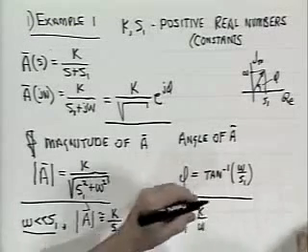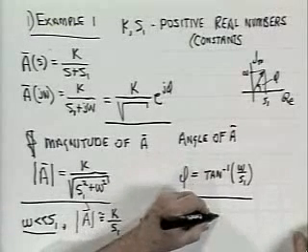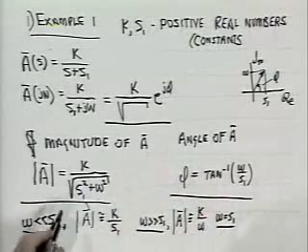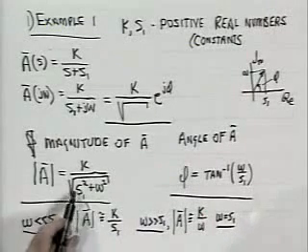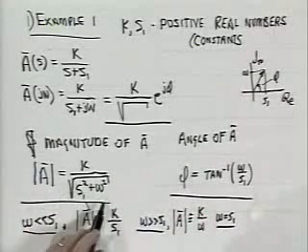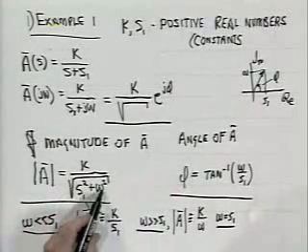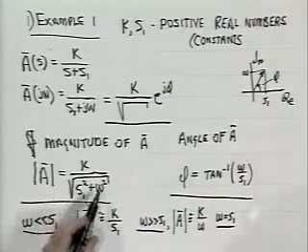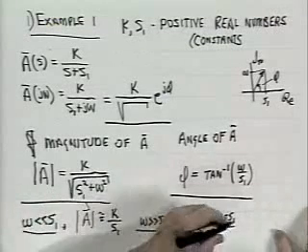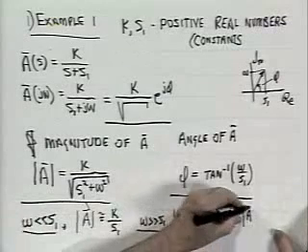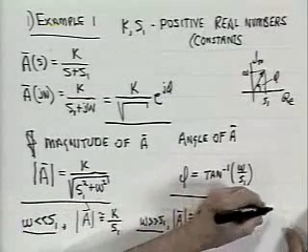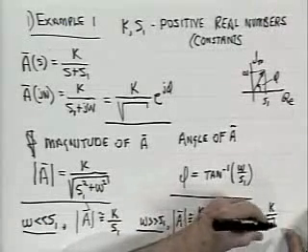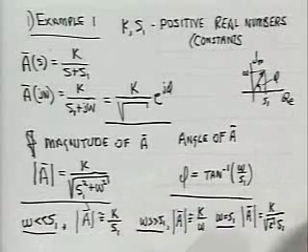And finally, we'll pick a particular frequency, namely omega equal to s1, in which case the radical becomes the square root of 2 times s1. That is, if I replace omega by s1, it's the square root of 2 s1 squared, or square root of 2 times s1. So at this frequency, the magnitude of A is equal to K over square root of 2 times s1.